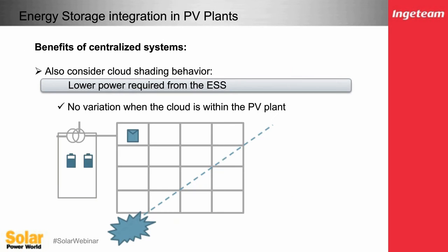And finally, when taking into account the centralized system, and what's also a benefit to batteries, consider the irradiance on a centralized system versus a distributed system. You have the clouds that are going to come over. At this first moment there are no clouds, and now you've got clouds over your array. In a ramp rate control scheme, this is the time where the DC of the batteries is operating to give you the ramp rate control down while you lose irradiance on your array.